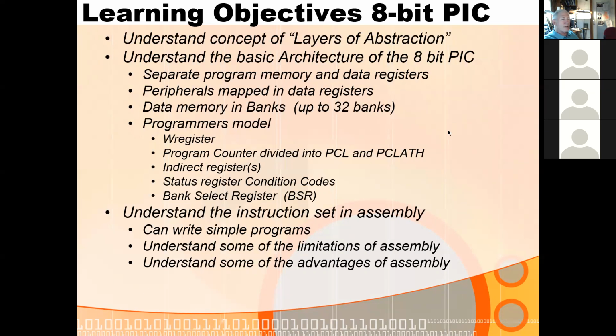So you might have to write that as an assembly language routine, and then you'll just call that function from C, and the rest of your code can be in C, but that assembly language routine will still execute exactly at the timing that you designed, and you can be very confident of that. That is the case actually with Microchip's touch sensing routines.